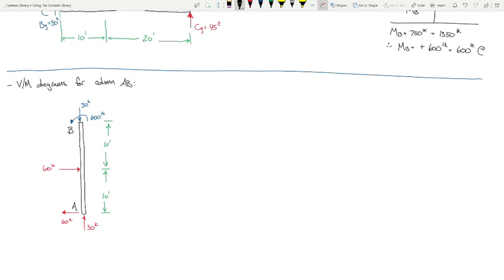But in a software program, the joints are not going to be lettered, they're going to be numbered, right? Because you could have a structure that has more than 26 joints, right? So what the software program will do is it will construct the shear and moment diagrams from the order of lower number joint to higher number joint, or in this case, lower lettered joint to higher lettered joint. So when I construct the shear and moment diagrams, I'll construct them over here. Normally the software package will just plot everything on top of one another, but